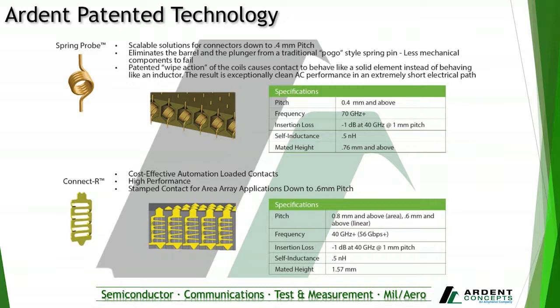When those beams deflect, the lance that protrudes from the ends of the beam comes in contact with the next lower beam. Again, here we see a wiping motion occur at the contact point of the lance to beam, and during that wiping motion, we also get a twisting motion at the rounded point of the contact. The twisting motion provides the added benefit of wiping the contact pad of the PCB and provides an oxidation scrubbing effect.